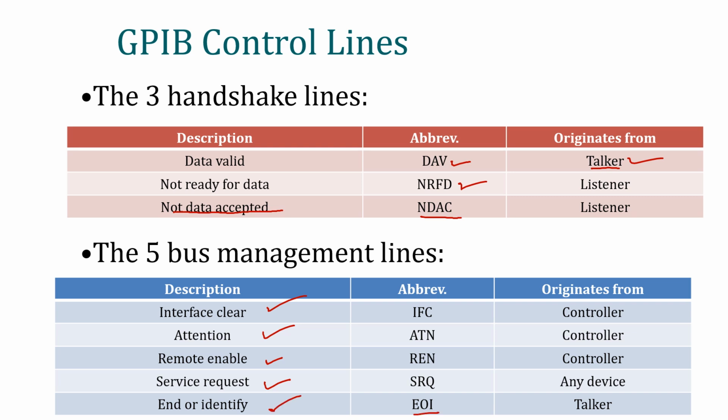So, there are 2 typical signals. Let me explain. The first, which is more important, is attention. Whenever the controller wants to get the attention of the talker and listeners, whatever function they are doing, first of all it sends the signal attention to a particular listener or talker or machine. Then it starts interacting through handshake signals. When the whole process is completed, it sends the signal end. Okay. Now, the data packet transmission is over. So, these are the functionalities of different pins and lines.